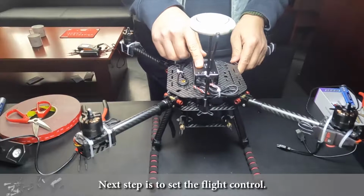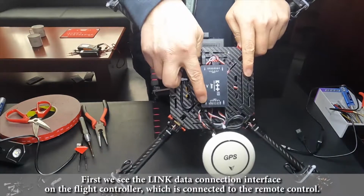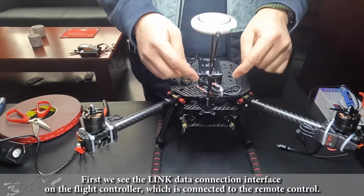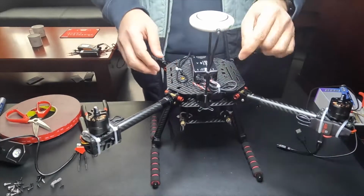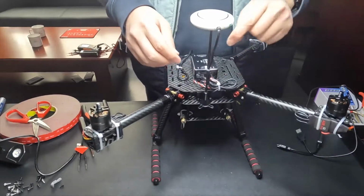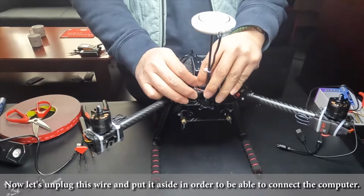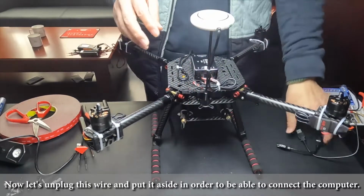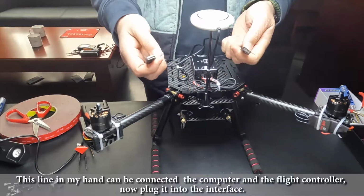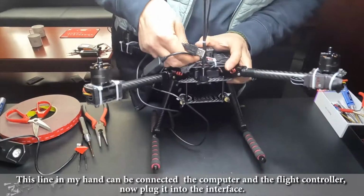Next step is to set the flight control. First we see the link data connection interface on the flight controller, which is connected to the remote control. Now let's unplug this wire and put it aside in order to be able to connect the computer. This line in my hand can be connected to the computer and the flight controller. Now plug it into the interface.